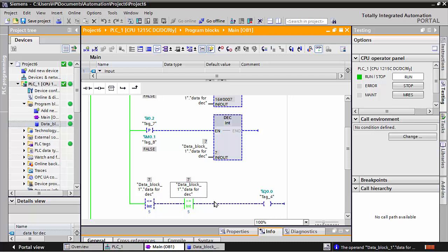This logic you should understand. When I put the count, I give direction that I need 5 bottles or whatever things, I need my Q0.0 to be stopped,